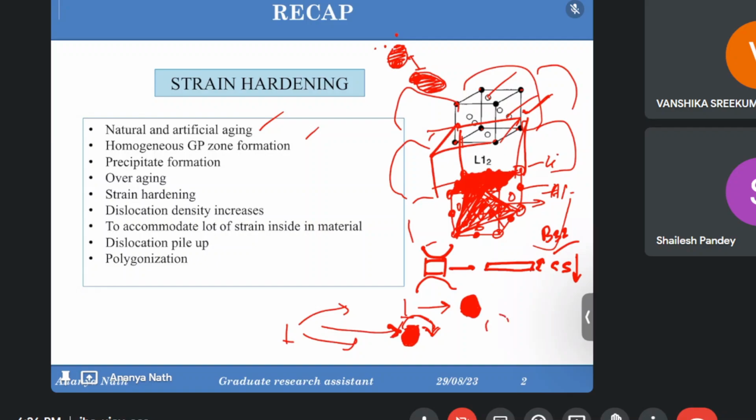if somehow this solute is sheared and gets halved by the movement of the dislocation, the surface area increases. In layman's terms, this dislocation now needs much more activation energy to overcome the whole surface area. That gives us the surface energy. So now the dislocations cannot move, and ductility is something which is defined by the dislocation movement.